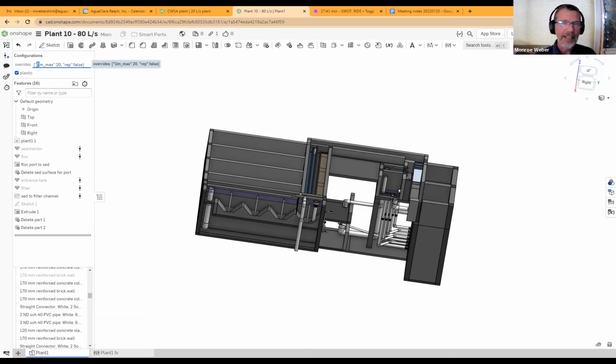And then the M after that Q stands for milli. So this is milli flow rate. So the default units for flow rate would be cubic meters per second, because it's just standard SI units. And then a milli of a cubic meter is a liter. So QM gives you liters per second. So I can enter 20 in there, and that gets processed into code as 20 liters per second.